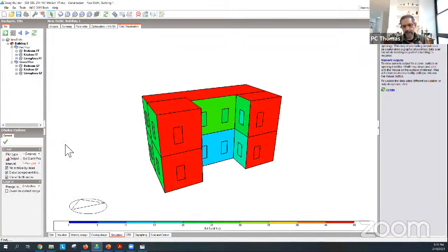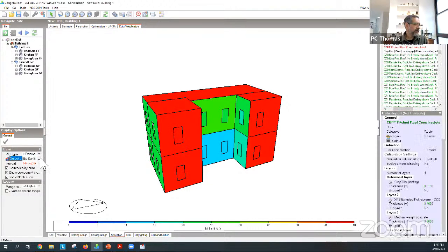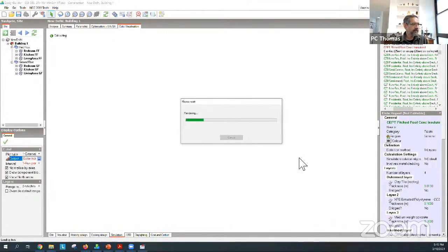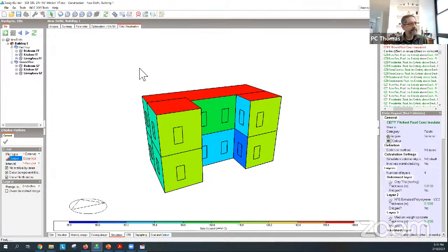So we ran it from 1st to 31st of March. For the entire run period, it's giving me external sunlit fraction, external surfaces. What I want is the solar incident on the outside. So here is my solar incident radiation. Now to do this, before you make the simulation run, you must switch on the surface variables, okay?